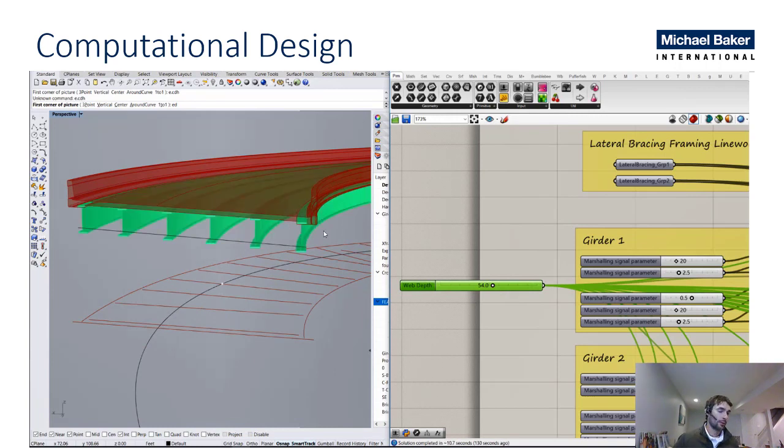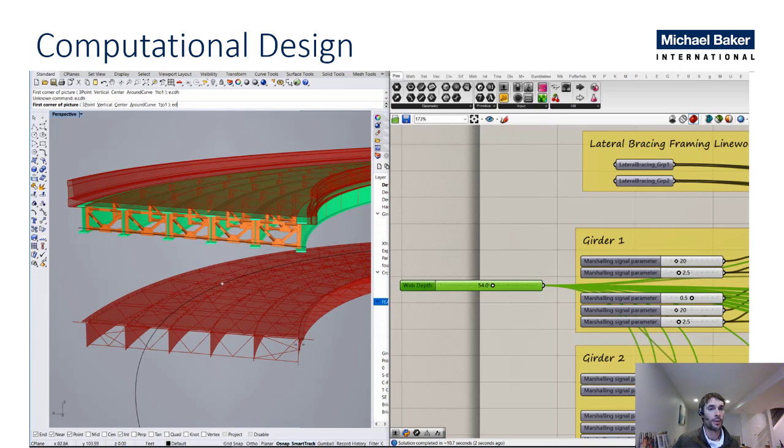Not only do the physical girders update, our cross frames that are applicable to that update as well. So they know they need to stretch and get larger. That geometry needs to change, and the logic behind that needs to change. But not only that, our analytical model that's tied to that below also updates as well. Again, we're tying that in.